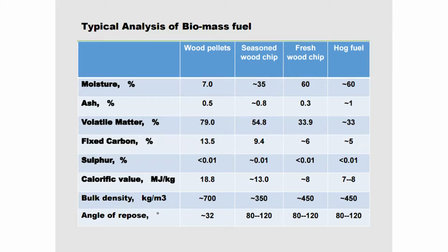Okay, ask questions. Tell me the calorific value for the dry wood, please. For the dry wood, yep. Depending on the moisture, if I come back to one slide, if you talk about 35% moisture, the high calorific value is around 13 megajoule. Yes, it's moisture related. On the dry basis, for the clean wood, around 20 megajoule, put it that way. So whatever the moisture, you will always convert back to that basis. Thank you. Yep. I like that, further questions on the way. It's too much information.